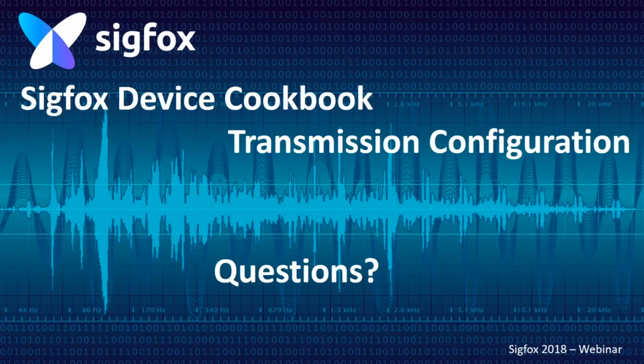But you don't send a Sigfox message directly to a satellite. You send the Sigfox message to a base station, which is itself connected to internet with a satellite connection. This is very different, so be careful not to mix stuff. We've announced some stuff to work with satellites, but this is something coming in the future, and you will hear about it soon, or in a couple of months. You'll see. But as of today, with the Sigfox protocol, you always send a message from your device to a base station connected to internet with either DSL, 3G, or satellite connection.